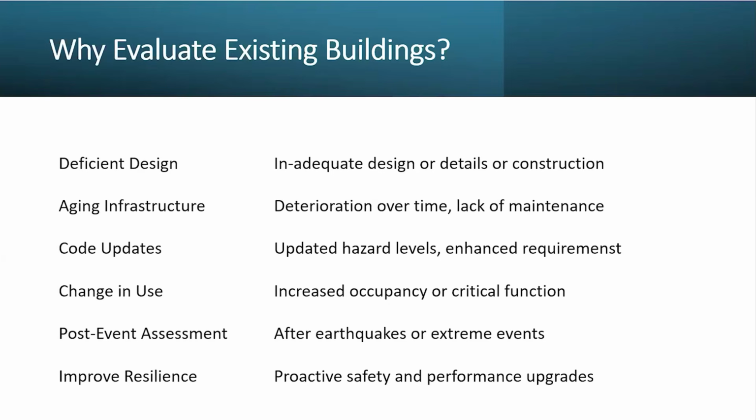Changing use is another reason: we change a building from residential to office, or office to residential, hotel to something else. That also makes the structure more vulnerable because the demands are different. Then there is post-event assessment: after an earthquake or extreme event, buildings may have undergone some damage, so we don't know what the current status is. And we may just want to improve the resilience. Many clients, before they occupy a structure, want to make sure that it is safe, so they want to evaluate the resilience of the structure, which is beyond just strength or safety. These are some of the reasons why we need to evaluate the building.